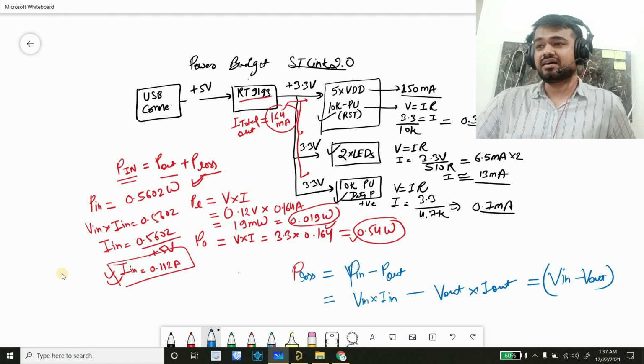I was thinking of it as an IC or something with a complex circuit, which works like a transformer, where power output is equal to power input, but there will be some efficiency thing. Okay, but I'll tell you what efficiency means for LDO. So here this will be multiplied by I out.